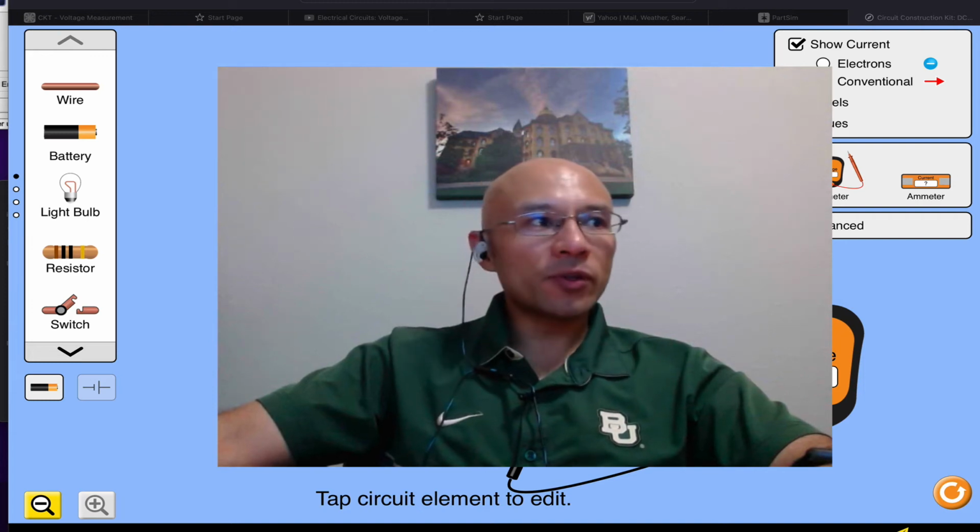In this video, I'm going to show you how to work with a ground in a circuit. This gets us single subscript voltages, which are new since I've taught you to think about voltages as always double subscript quantities measured between 2 points. Even though we're going to single subscript, we're always measuring between 2 points. It's just that 1 point is our common reference. It's the reference voltage for all other voltages.